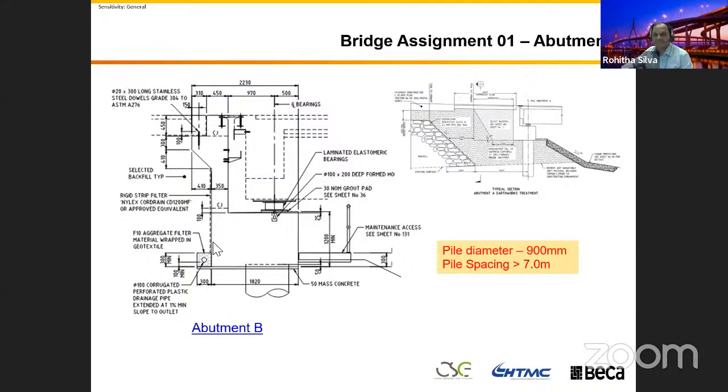If you are a smart design engineer, you can say, I just put minimum rho considering the size of this beam. I use a strut-tie model because it's a non-flexural member. I will get my rho and use that as a percentage, and I am going to do my cost estimate. It's right, it's correct.